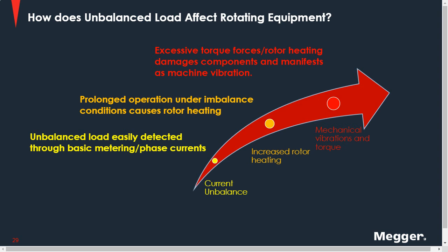So, by now we're well informed that the presence of positive sequence components occurs in a balanced system, and it's built into the design specifications of the equipment. And I think we're well informed now that the presence of zero and negative sequence components is an indication of abnormal conditions on the system. And what happens if we ignore it? Well, if we ignore it, of course, we're going to have the same issues that they had back in 1913,